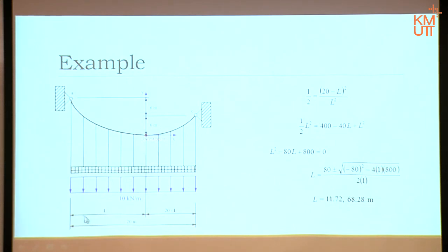So it has to be something in between A and C. If L becomes minus, it can only happen if you pretension the cable, meaning you did not look at the curvature like that; you cut it before the lowest point. It doesn't happen naturally. You would have to pretension the cable.